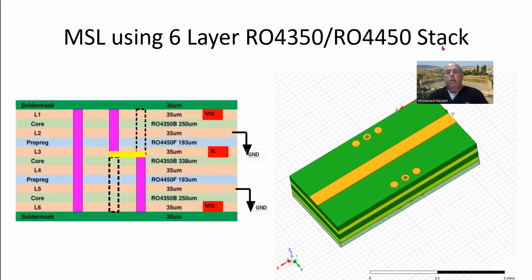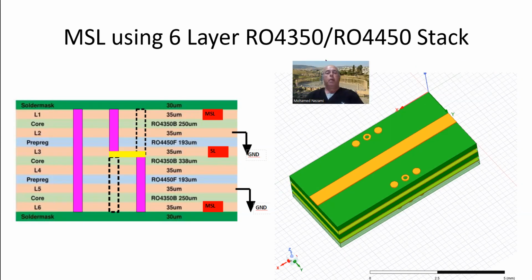So anyway, let's get back to designing our crossover. The first thing we're going to do is come into the substrate that I chose. First of all, what I would do is lay out a straight line and make sure that the width that I've calculated is correct.